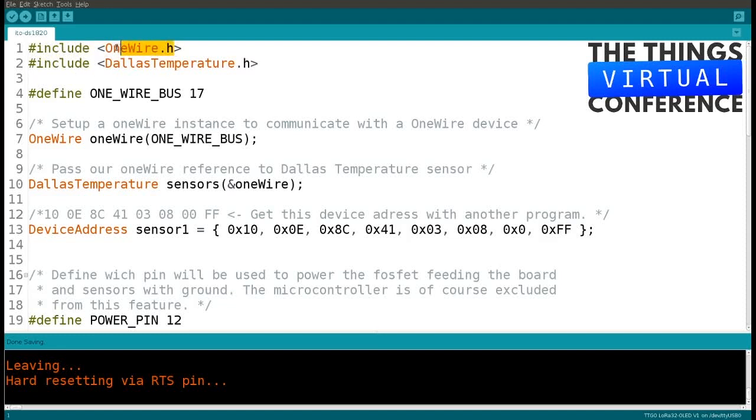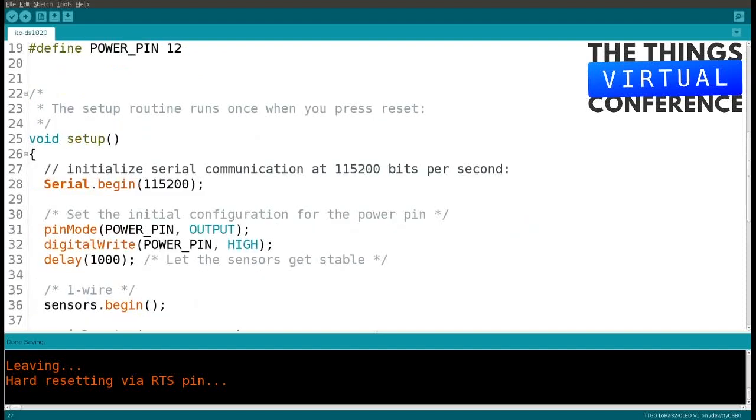And often in these .h files, you will find the possibility to do some settings. That could be IDs, in the case of BME280, etc. And here we recognize this ID we found before. I already put it in here. It can be different. The 0x just tells the software this is a hexadecimal number.